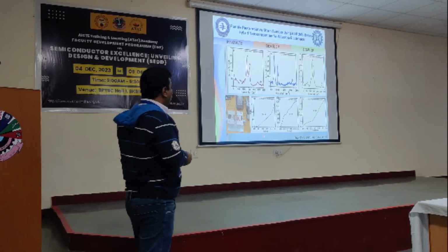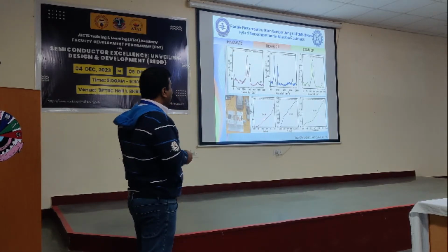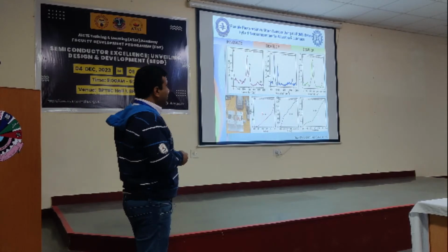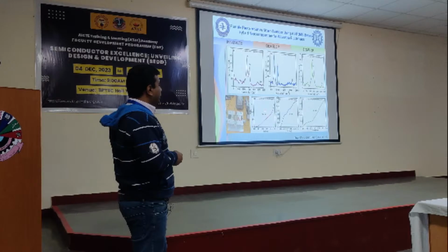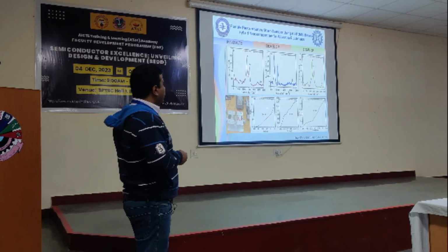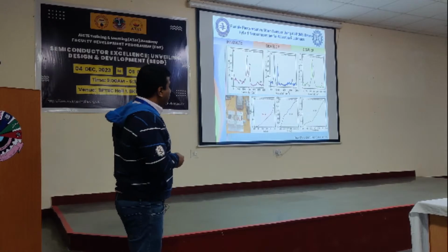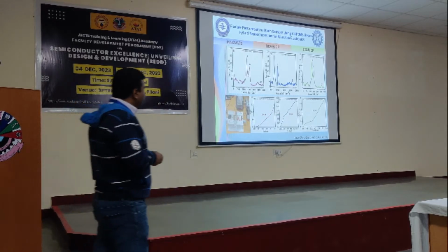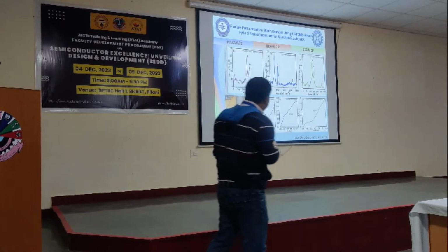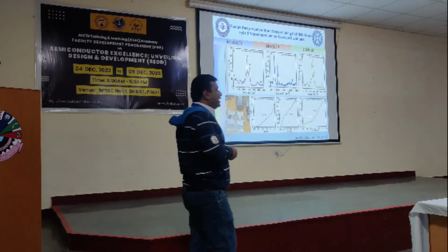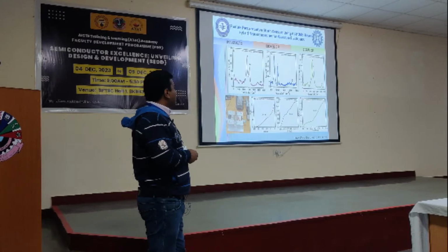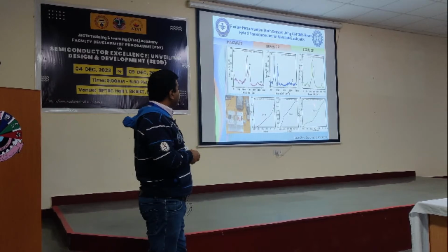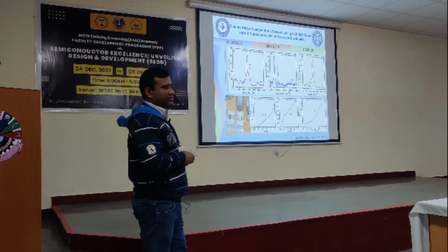You see, when applying strain, in this case you found the gauge factor. Gauge factor is nothing but the change in resistivity upon applied pressure, right? Change in resistivity, delta R by R, divided by applied strain. Gauge factor 188, this one 184, 104, 184 something like that, and this is 221. So the highest gauge factor you can achieve is in the case of silver nanoparticle and GNP based devices. So you can say that this device is actually showing the best result. In that case, this third one is your very suitable or best device.